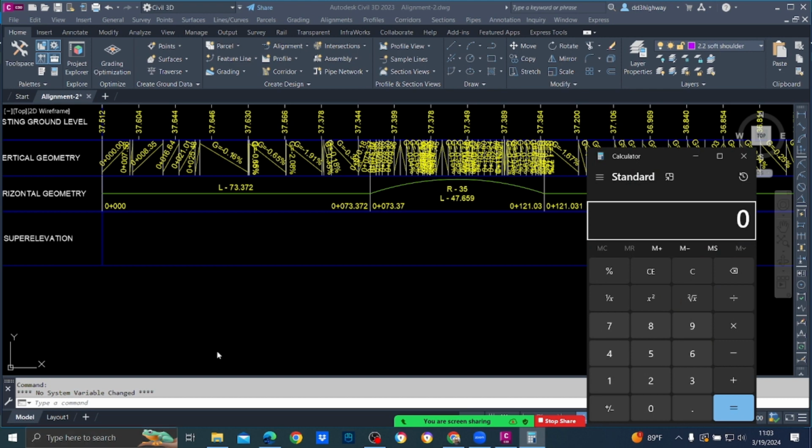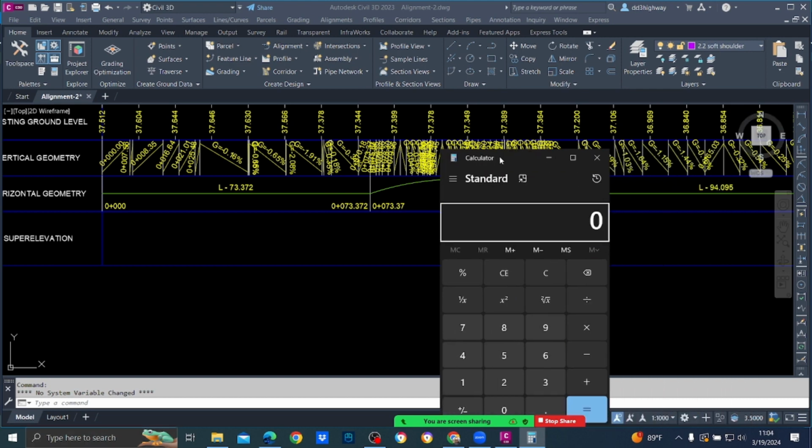Okay, what is LE? LE equals W into E plus N divided by GR. Agreed? So what is your W? 3.5 plus 1.5, that is 5. 5 into E. E is super elevation, say 2.5. Then normal cross fall is again 2.5.